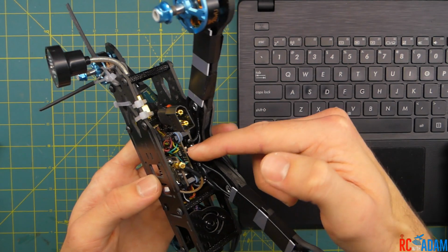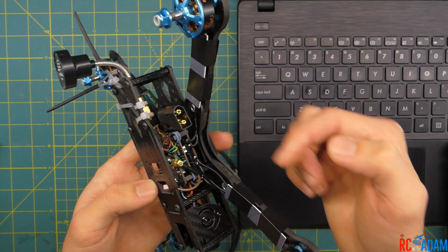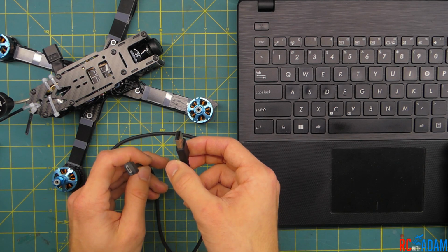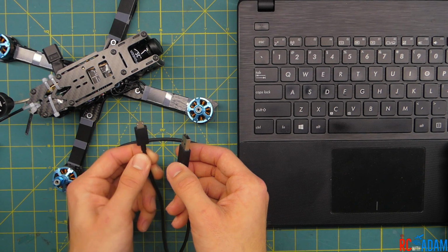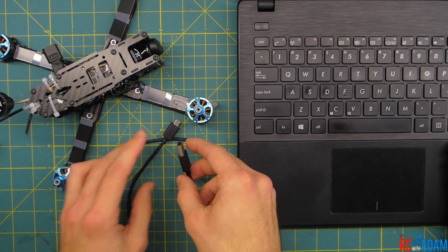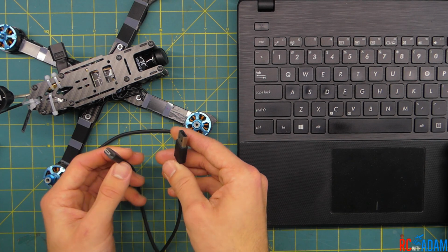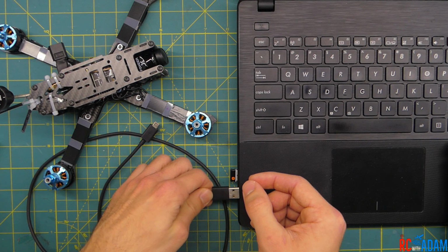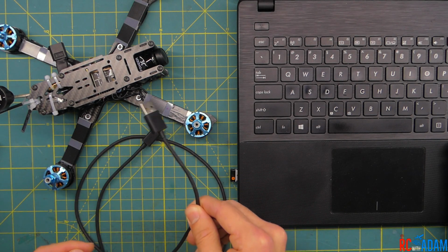Any other time you don't need to hold down the button, but if you want to update the flight controller, you need to hold down the button as you plug in the cable. Speaking of the cable, you want to make sure that your USB cable is capable of transferring data, and not just a power cable. So if it seems like you have everything correct, and for some reason your quadcopter is still not talking to your computer, it might be your cable. It could also be a low quality cable, or the physical cable connection in your laptop just might not be good. So try switching cables if it doesn't work.